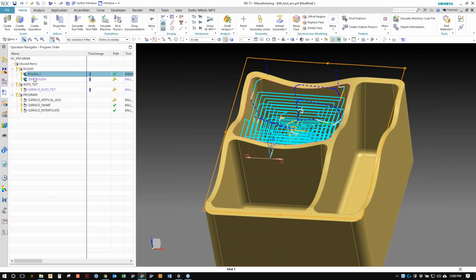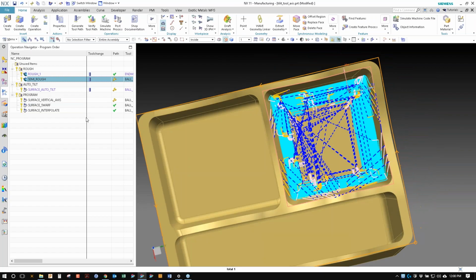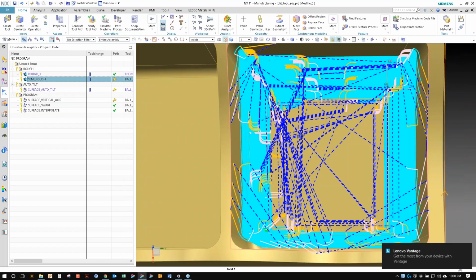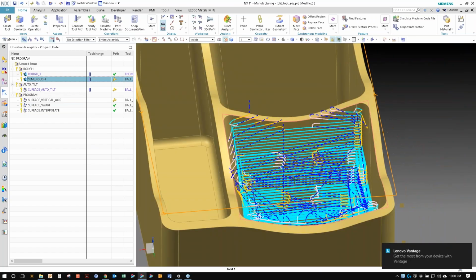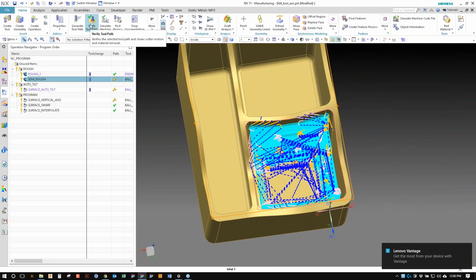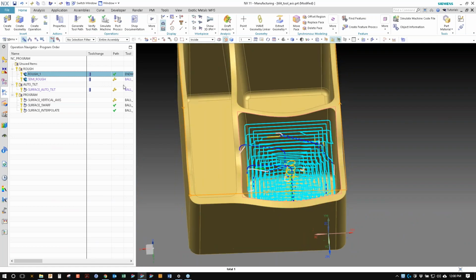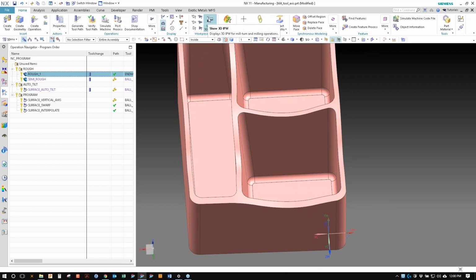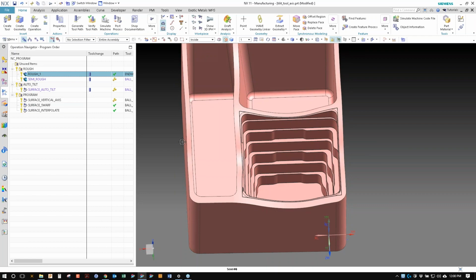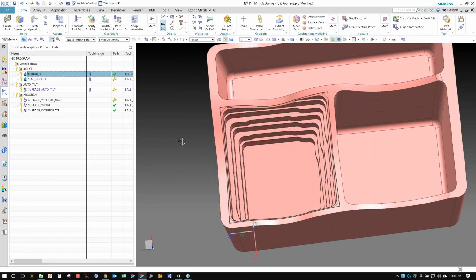I know we're wrapping up here, so I'll just glance over this other part. You can use it. I didn't. I allowed some direct transitions here, but this is a roughing toolpath, so you can use it with cavity mill. You just have to make sure you're using a ball mill. And so I roughed the cavity out with a regular end mill and left collision checking on.